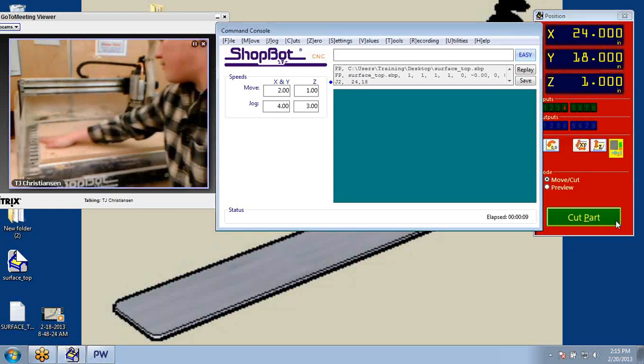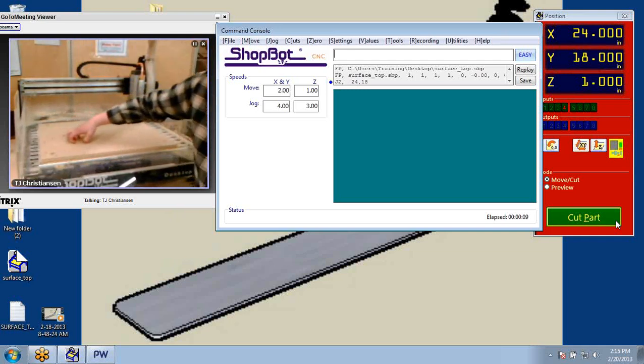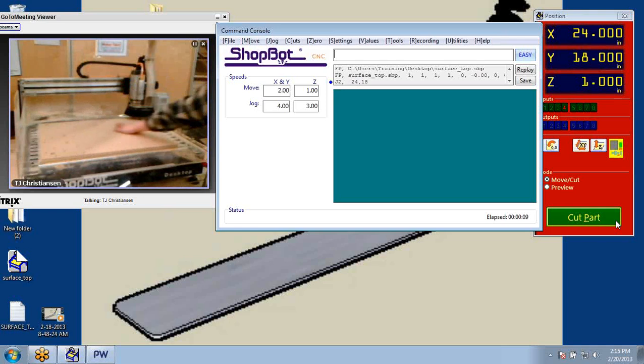I can see passes with my lines from my toolpaths, and that's fine. You can see them. If you were to take your fingers like this and try to move them along, and it feels like you're running along a washboard, like dink, dink, dink, dink, you might have your spindle out of whack. Mine cut great for about a year. Then I ran the spindle into a clamp, and it knocked my spindle a little crooked. So I had to come back in here and loosen up some bolts and fix that so it runs perfectly flat. You're never going to get it so you don't see any of the lines in there. You're going to see lines in the table, but you shouldn't be feeling a washboard, and that just means something's out of adjustment. And it happens. I'll admit it, I've crashed my tool and knocked it out of square, but you don't have to. So that's simply surfacing a table.